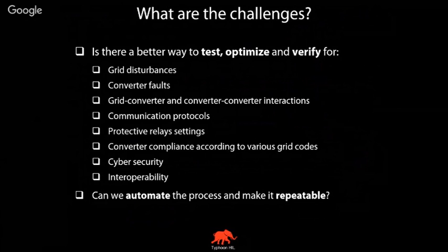These new emerging grid codes, India is also not a stranger to this, especially with this need or this resolution of your government to install about 200 gigawatts of renewable sources within the next 7 years. All these sources will have to be tested against particular grid codes that are becoming more and more complex by the day. We are speaking about tests like low voltage ride-through, frequency ride-through, anti-islanding operations.